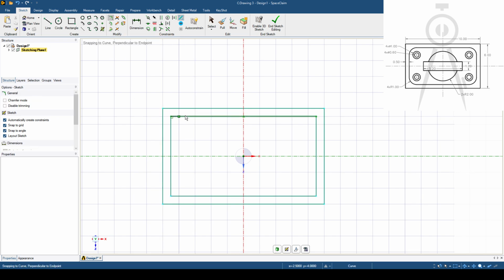From there we click on this line and just hit this side without clicking anything, and we write 1 millimeter as a radius and then enter. As you can see now we have this corner and the extra edges were removed automatically. We do the same with the other 3 corners. So I choose this line, this here, and 1, and enter. This line, 1, enter. This line and this line, 1, and enter. Now we have this more simplified with these corners, and it looks better.